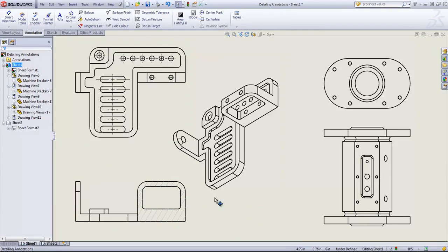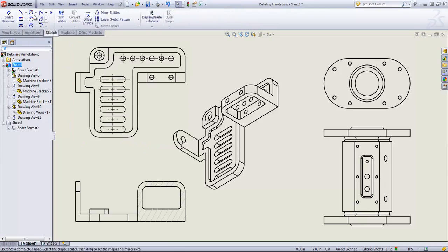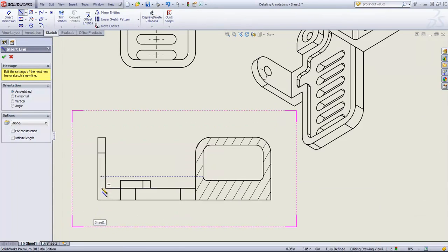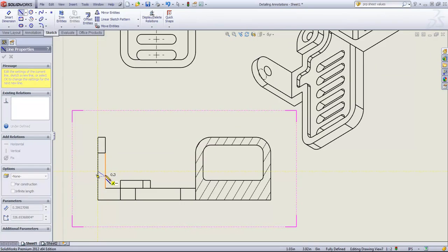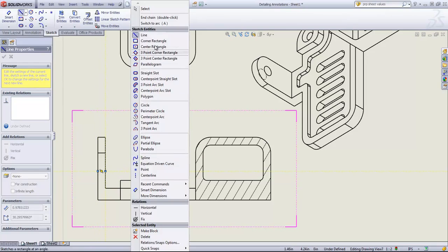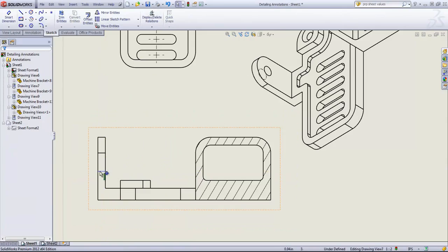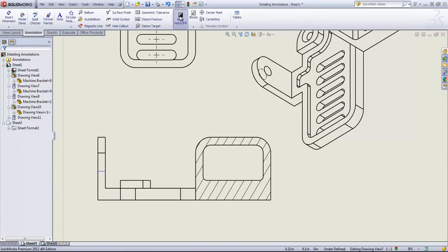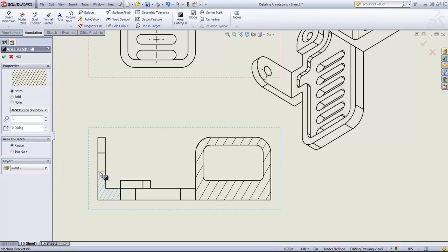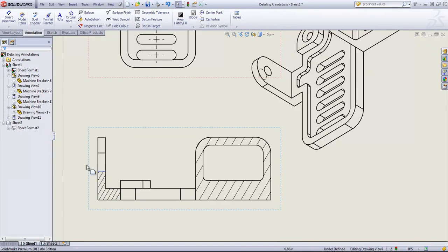The area hatch fill is also a useful tool if you're trying to show, for example, a fill point. So if I was trying to fill up something with liquid up to a certain point, I could draw a line breaking up that area and choose the area hatch fill in this area, and it's going to fill up to that line.